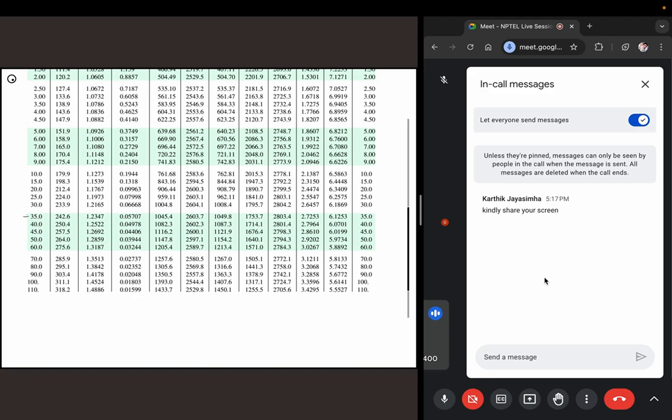At 38 bar, here we have 35 and 40. So again, we have to do a linear combination. These are the Uf values and these are the Ug values. We know that it is in the saturated vapor region, so these are the values I should be using. So we know at 35.